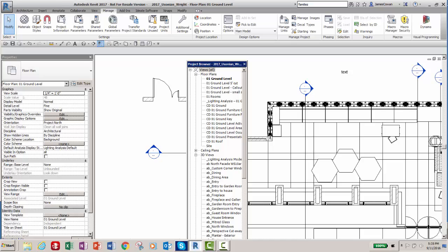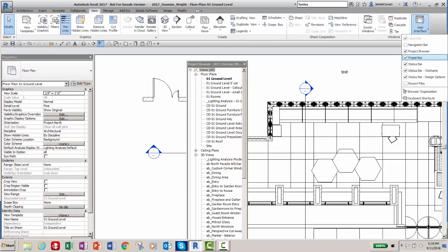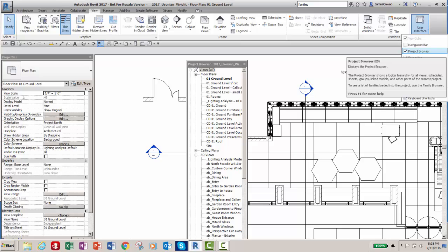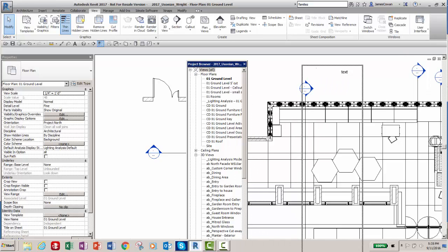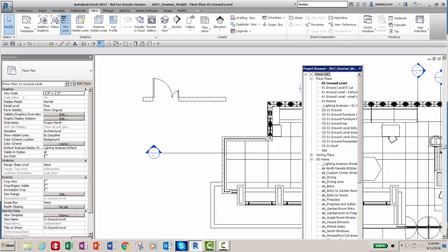So for example, if I look on the user interface, if I go to the view and I look at user interface, this is typically how you can turn things on and off. I've added that one already myself as well. I typed in my setup, I have BB as the project browser. So I want to show you where you could create them in order that you know how to add them. Let me drag this over. Not a good idea to leave them floating like that because it uses RAM. Much better idea to move to the middle center of the right hand side and release it.